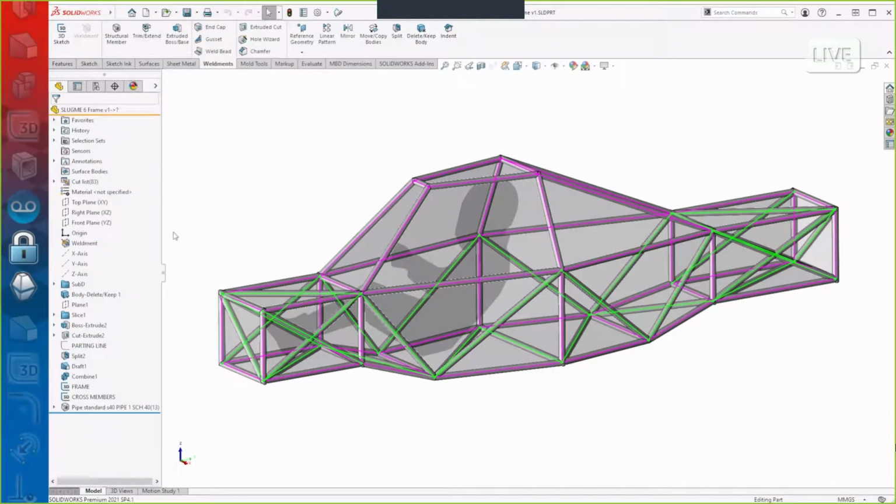Here's a huge tip, and something everyone should be aware of. The first thing you do when you go to make changes is roll the rollback part all the way to the top, right? Then you start at the top and work your way down, because you follow the same order the part was made in the first place. But there are some things we know we're not going to be modifying, and that includes the slices and all that. So I'm going to drag this yellow bar up at the top down below the slices, and then you get this little lock icon.